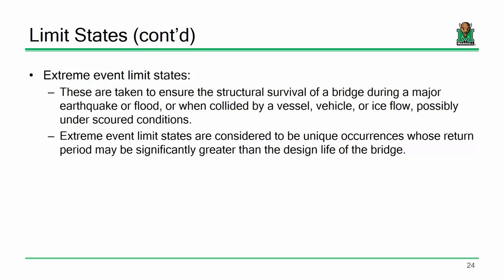Now, here's the thing for buildings, and I use this analogy because I think it's a little easier. For buildings, it's the same. If an earthquake hits a building, there's no earthquake monster pushing on the building, okay? It does not apply a force to the building. It accelerates the building. I mean, why do you fling forward when somebody hits the brake? It's because the acceleration suddenly changed.